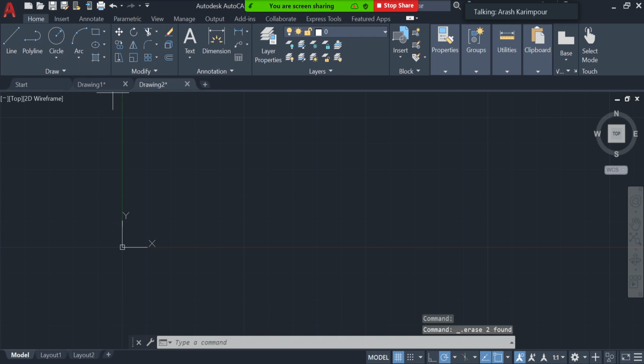One other thing I want to mention is that, again, assume I want to start the line from 0 0. So I put the 0 here, but by mistake I put 10 here, and I go there and put 0 here, and now it's going to start from 10 and 0, but I want to start from 0 0. If I press the tab again, it goes back to the first one. If I keep pressing the tab, it's going to switch between these two numbers. So if you enter the number and later find out that was the wrong number and you want to fix it, you just keep pressing the tab until it goes to the value you want to update. For example, I put 0 here, and then again 0 here. You can keep pressing the tab until you fix all the numbers the way you want.